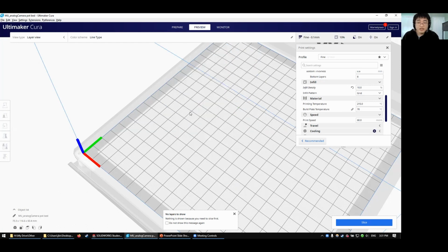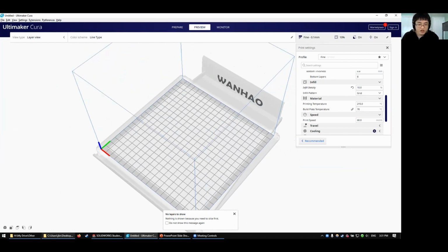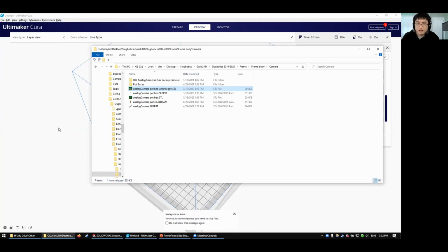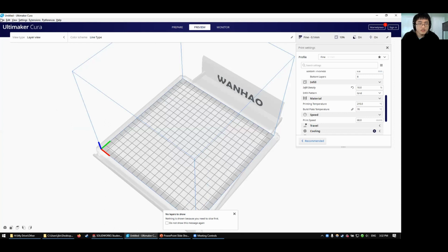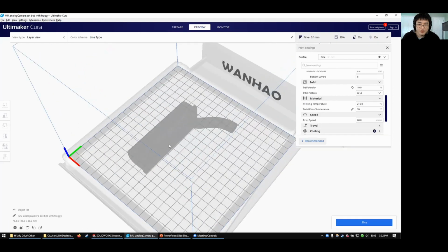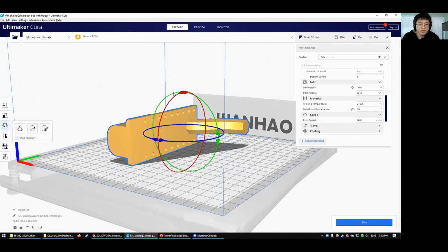Good question. Well, let me do that. So most of them, they're pretty beginner friendly. You can just drag and drop stuff. So I have here an STL file. Pretty much any slicer, Ultimaker Cura, Prusa slicer can process STLs. You can just go to File, Open Files, and select from there. Or you can just drag and drop for the most part. I just hit drag and drop. And then if I'm going to prepare, it shows me that's the file. You can click on it and modify it, and it should be good.